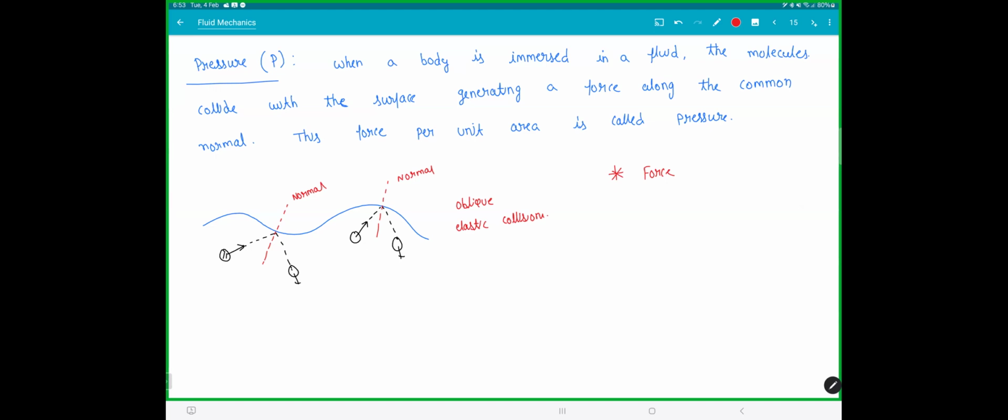The same way, by definition, the force perpendicular to the area per unit area is called pressure. But in books and all, you will see as if pressure will always exert a perpendicular force. It doesn't make sense, but okay. Mathematically it works. So the force due to pressure is always perpendicular to the surface. It doesn't matter what kind of shape you take and put it in a liquid, you can be sure the force is along the normal. So if you put some amoeba shape like this in a fluid, the force will be perpendicular to the surface.